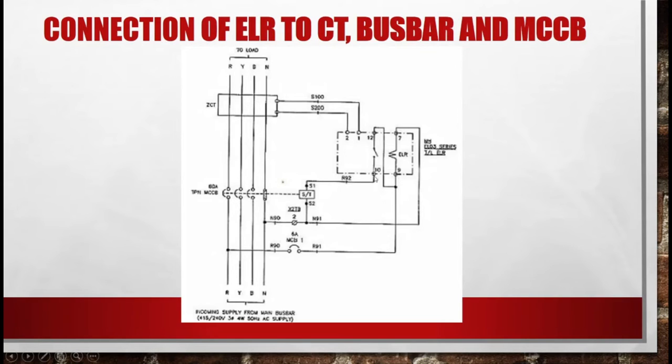Pin number 10 here is connected to the shunt trip coil and to the MCCB for the normally open contact, while pin number 12 here is connected to the red phase line in order to activate the switch or contact.